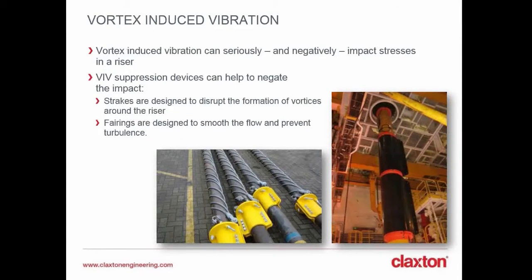Vortex-induced vibration, or VIV, is an important source of fatigue or damage in offshore oil exploration and production risers. It can cause serious stress to the riser conductor systems, either by reducing the fatigue characteristics of the system, or in some extreme cases, by causing physical damage to the riser and its components as well. The vibration induced in elastic structures by vortex shedding is of practical importance because it is potentially quite destructive to pipelines and marine risers.